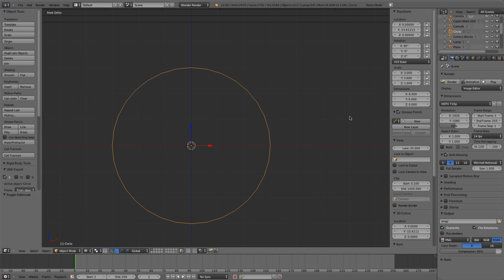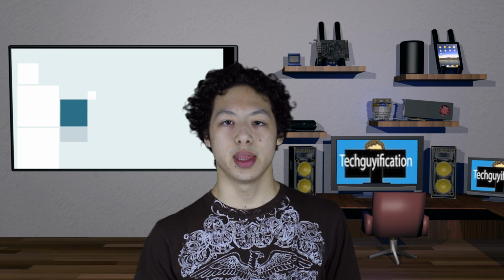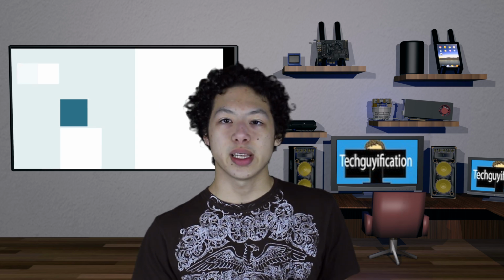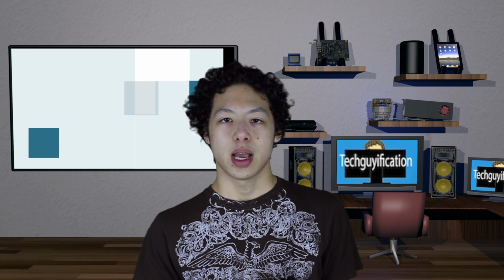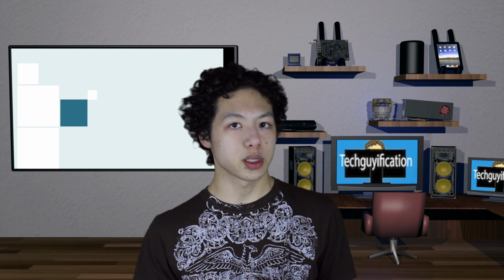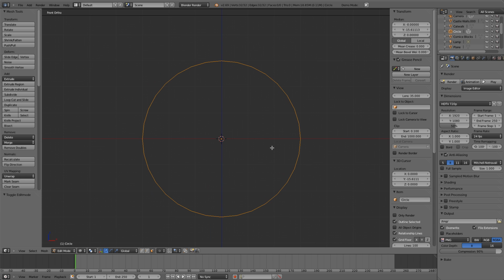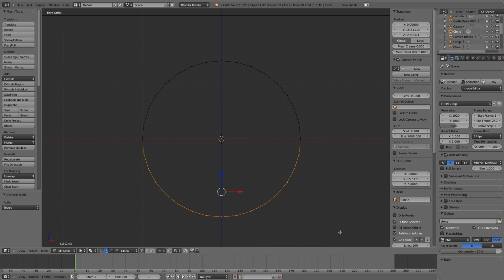Now with the circle selected, press Tab to go into edit mode, and then press A once or twice to deselect any vertices that might be selected, and then switch into vertex selection mode, which you can either do at the bottom or the shortcut is Control Tab. Next, press B to do box select, and then box select the bottom half of the circle. Now press the X key and delete the vertices.